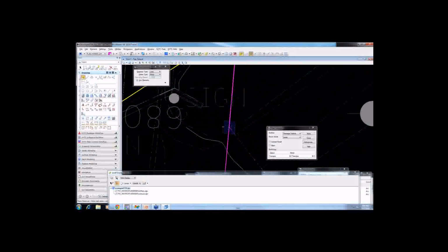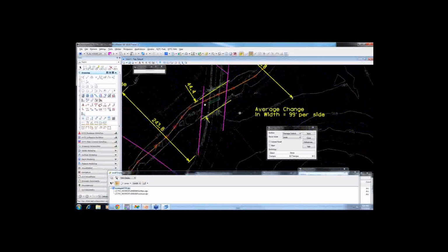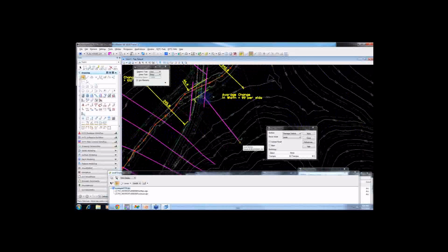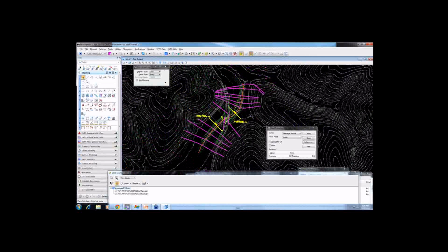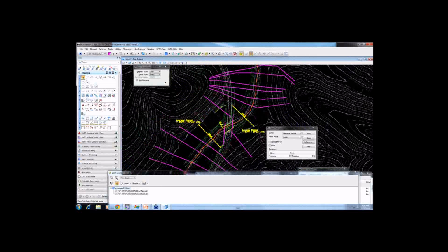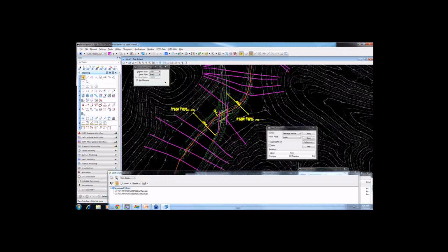And then come up this side of the floodplain here. And that would be my section. I could go back and trim out those construction lines. But the idea here is that water's flowing this way, so it's perpendicular to this line here. So that's how I would lay out those two bridge sections.